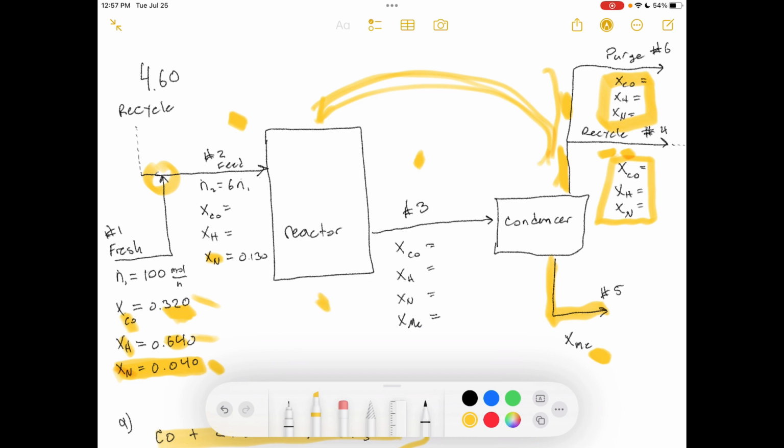If you're putting nitrogen in, nitrogen also has to go out, right? So if you only had this stream and you didn't have a purge stream, there would be no way for nitrogen to leave the process, okay? And then nitrogen concentration would just build up until either you had a pressure explosion or you just couldn't feed anything into the reactor anymore.